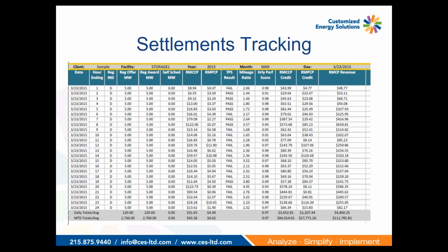Are you asking about the performance score? How do you calculate that? Is that the question? Was how do you estimate performance? I don't have the question any longer. Performance ratio, I think, was the question. Okay, so I think it's performance score, and in PJM there are three components to performance score. One is the correlation score, which is simply a statistical correlation between the regulation signal, which is Reg D in this case, and the response of a battery or a storage resource.